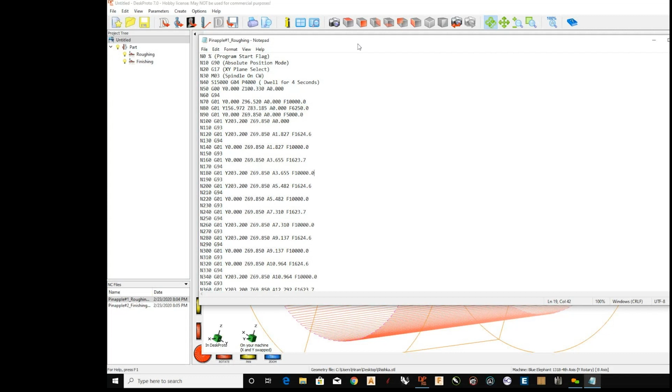Correct. So when you convert from degrees into inverse time machining, it converts those degree rotational axes into a higher feed rate, which you will see right here. So now it's more like turning the axis much more as RPMs instead of degrees.